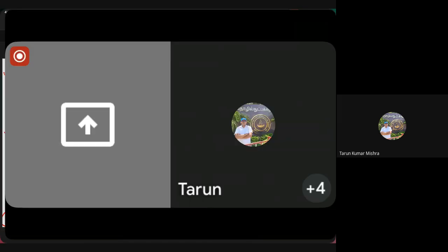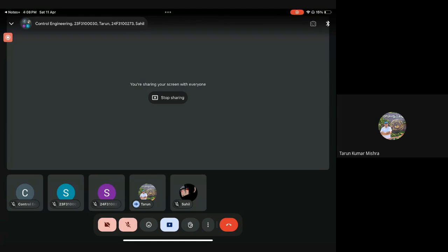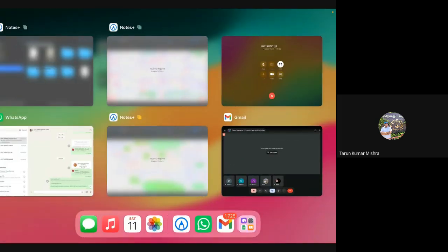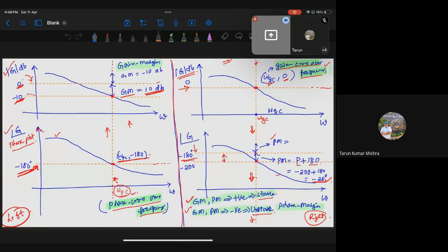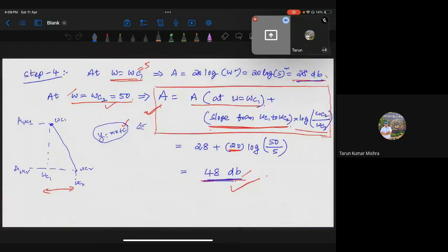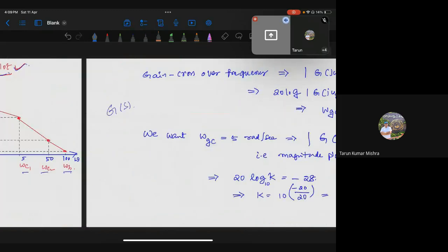And one from Nyquist, sir, if possible. Yes, tell me. So Nyquist also is a similar thing. We define the gain margin and phase margin, and based upon the plots we decide the stability over there. But mostly we depend upon the Bode plot for the gain margin and phase margin. Let me show you this example. I think I have that example also with the direct calculations.